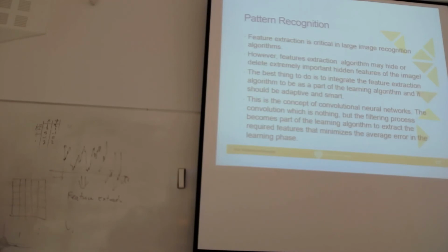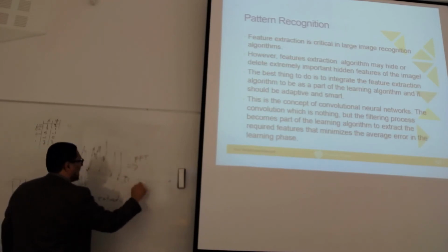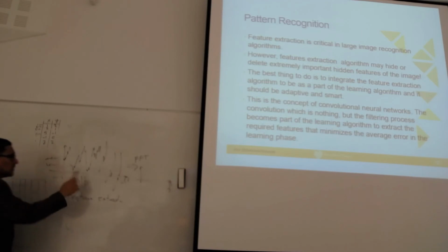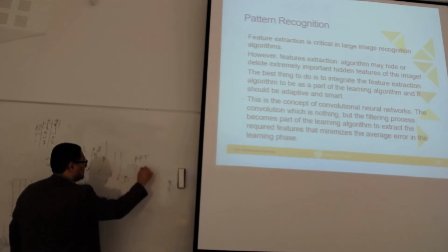Okay. What features can you extract from the signal? You can think maybe of some statistical information, maybe the mean of the signal, maybe the variance. However, this depends also on the signal strength. So you need to make normalization of the signal, but this might not be enough. So we need also to transform this signal to the frequency domain, like by taking the fast Fourier transform. Then we will have in the frequency domain the frequencies of this signal. So we have some certain frequencies, like you might get something like that, for example.